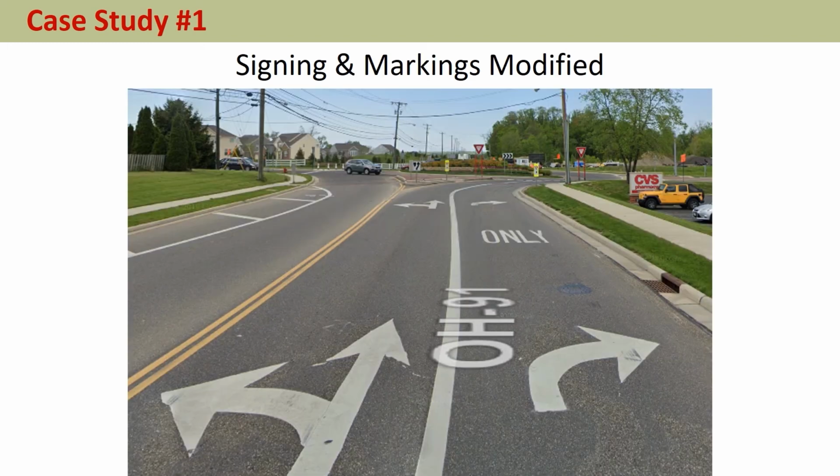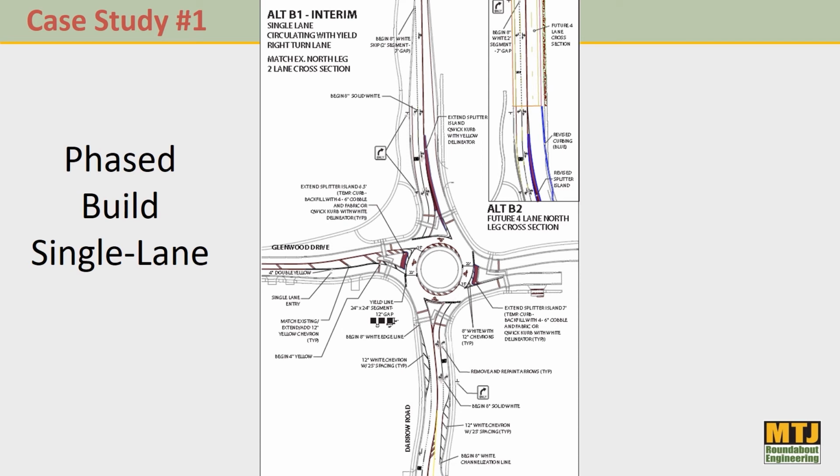And that's what it looks like today. We changed the official style arrows to standard arrows. We used the R1-6 style pedestrian signage, which is based on some research for that signage, to provide height variation to signing to improve target value for all signing on this project, and used conventions that drivers are used to as opposed to conventions that drivers aren't used to.